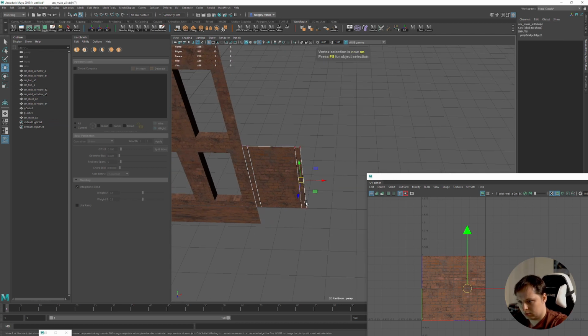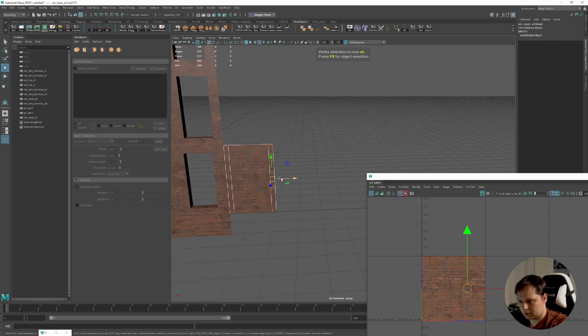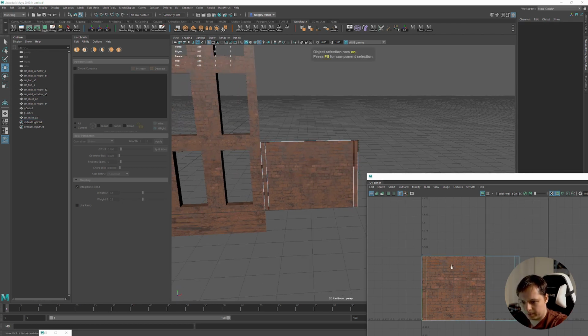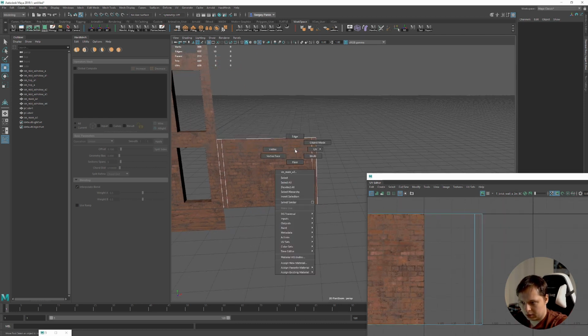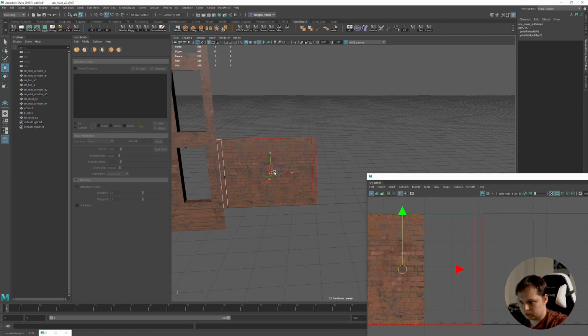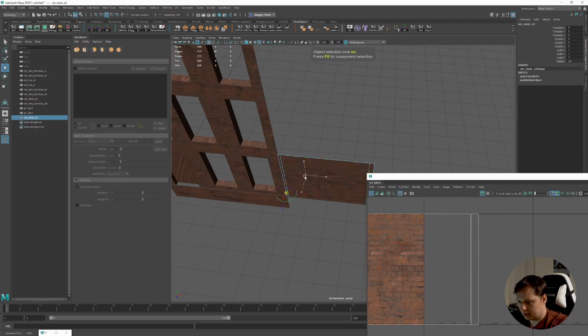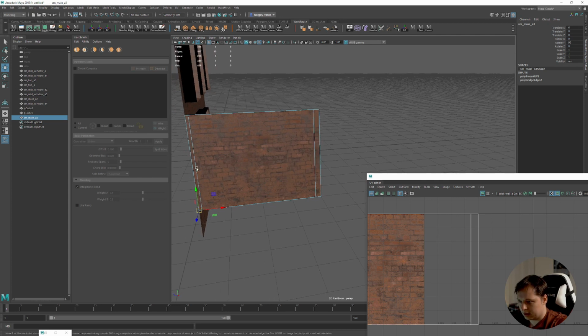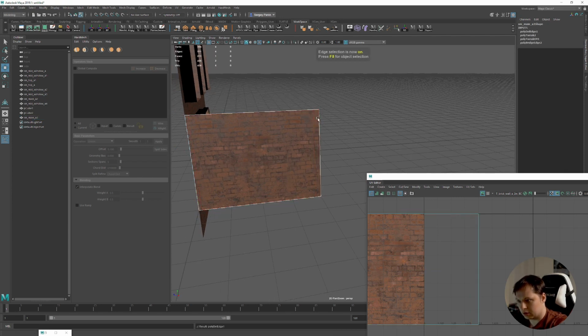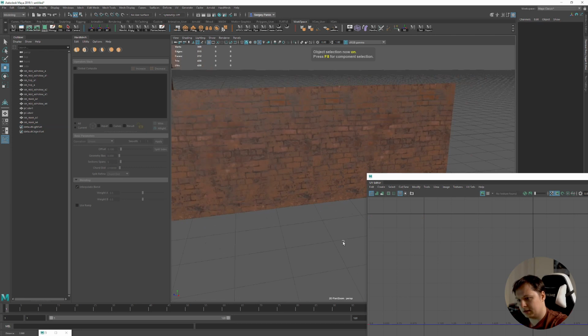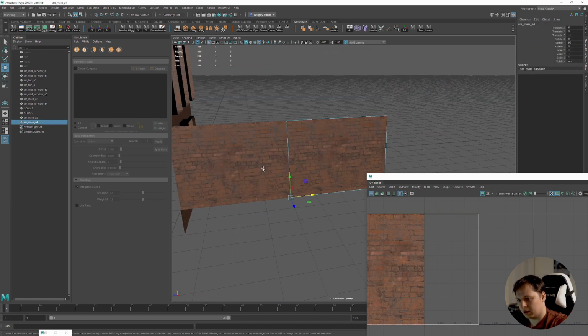What length? We want to have it 4 meters. Also in this case, the preserve UV command can be very useful, so you see it continues tiling how you want. And we now have it how we want. This is exactly what I wanted. And right now, let's delete these two edges. If I place it here, you will see a seam. So how can we solve it?